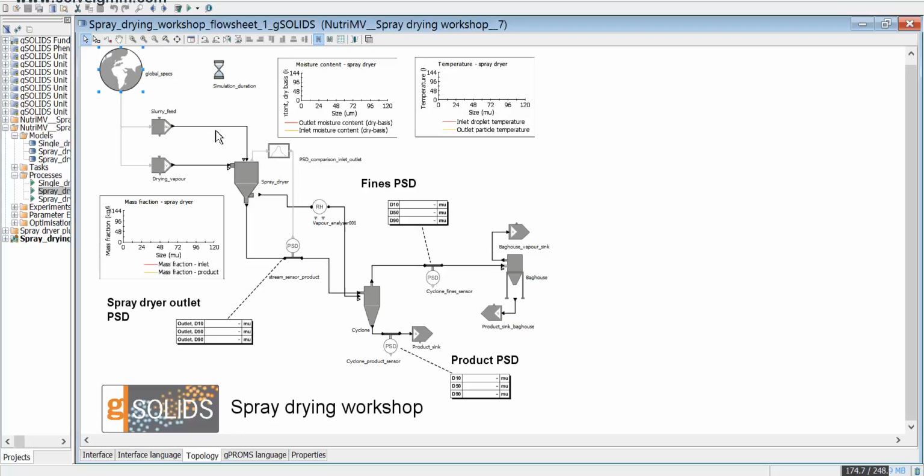The mechanistic model is used to simulate the process-product interaction and generates the critical quality values such as powder moisture, particle size distribution, bulk density, etc. From the mechanistic model, we build an optimizer in the advanced process control, and then we can optimize the dryer. This model-based environment allows us to do this readily and quickly and experiment with various optimization scenarios.